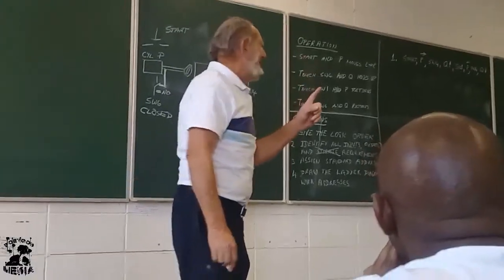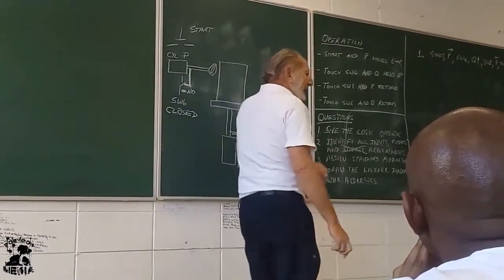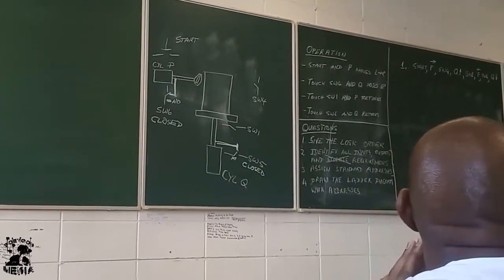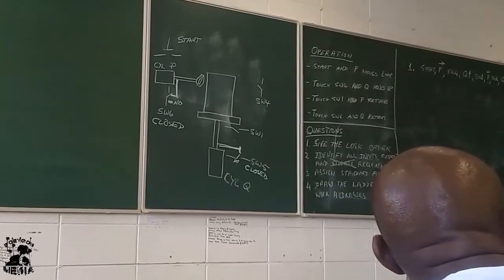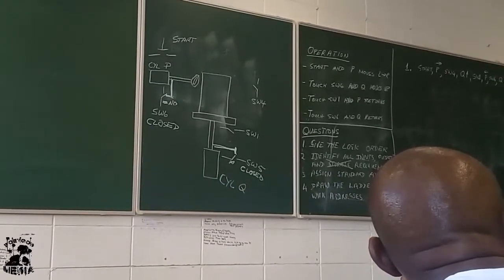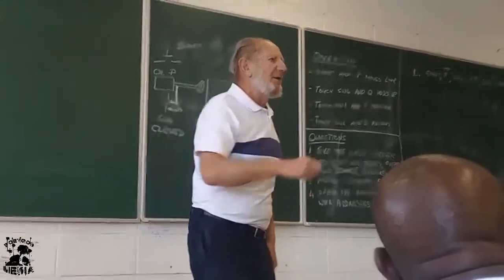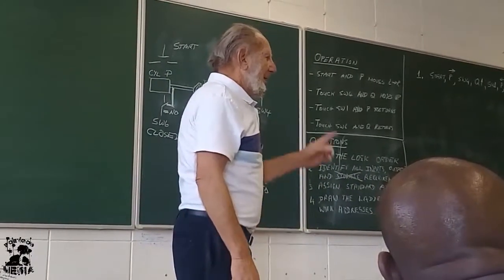We check that switch which is closed in the beginning. Does it remove power or does it apply power? If it removes power, no problem. If it applies power, we will see it in the next example, then there is a problem. Okay. But watch.